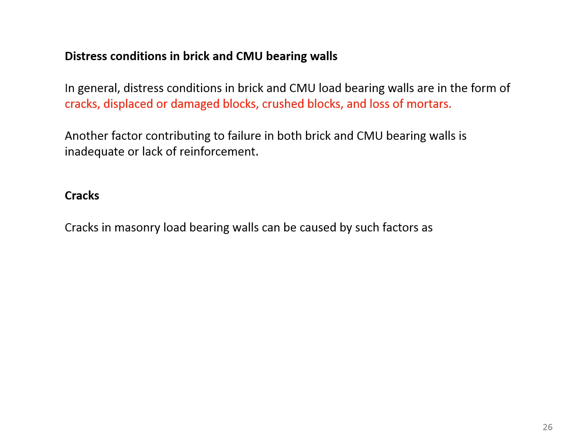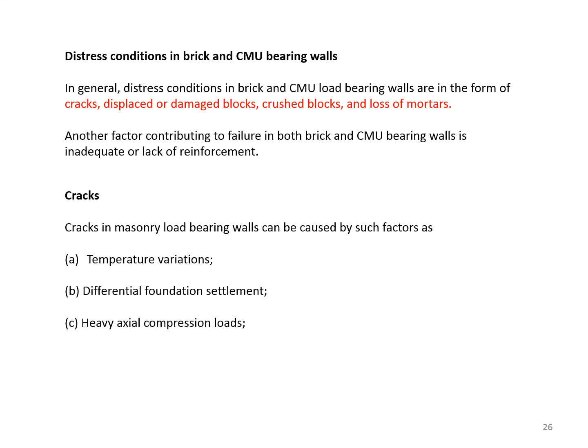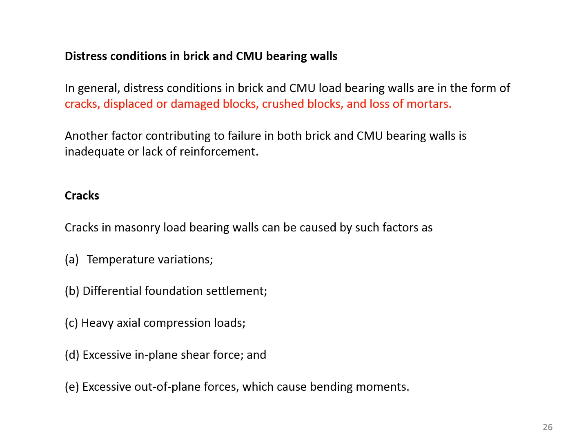Cracks in masonry load-bearing walls can be caused by such factors as temperature variations, differential foundation settlement, heavy axial compression loads, excessive in-plane shear force, and excessive out-of-plane forces, which cause bending moments.